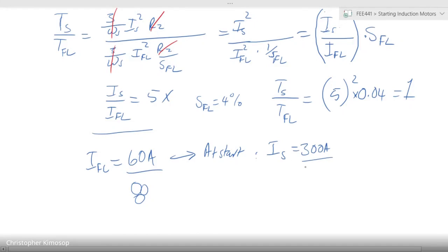If you require the same cables to carry 300 amps, they are likely to melt, okay? So you would then be in a problem that you would have to have huge cables that would be big enough to carry 300 amps, whereas 99% of the time, you only need them to carry 60 amps. Practically, that's a waste of resources, isn't it?